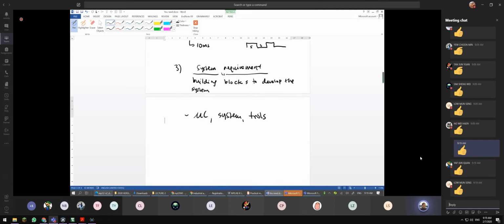Great. So these three steps are very, very important. Also, probably over here, after you discuss with the software engineer, you know that you need to involve a timer and some interrupt to make the system more appropriate. And we are not going to use a delay. We are not going to use polling, for example. I hope that all of you can differentiate between polling and interrupt.